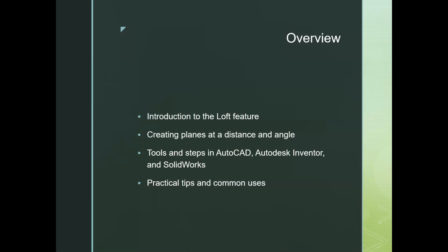Alright, so far what we've discussed is how to use the extrude command. And remember, the extrude command is really simple. We need some kind of profile, preferably a closed profile, and we need a direction to send it, or a vector, right? So we need those two things, and typically with the extrude command, we're extruding in a direction that is normal to the plane that we created in. And all that fancy word normal means is that it is perpendicular to it.